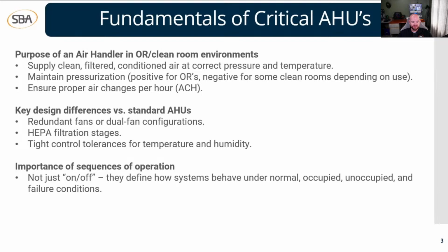The key design difference between an operating room or clean room air handler and a standard air handler is that in an operating room or clean room air handler, you would find a redundant fan or a dual fan configuration. This would be for if you had a fan motor fail during operating hours. This would be a fail-safe for a secondary fan to come on so that you're still providing air to the space if you do have a failure of some kind.